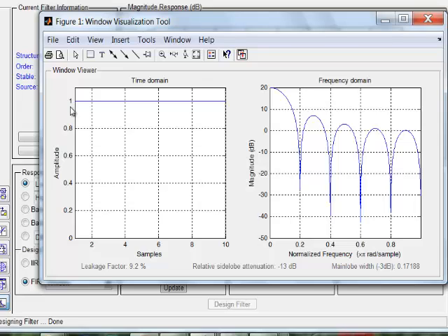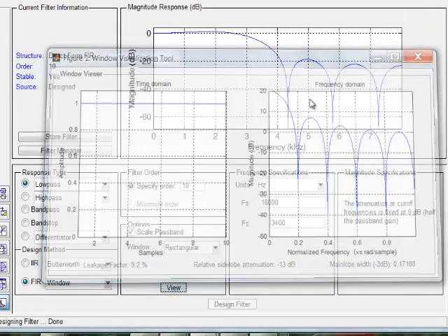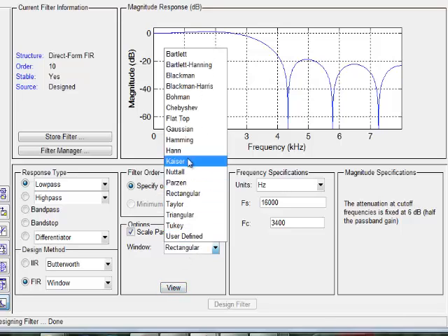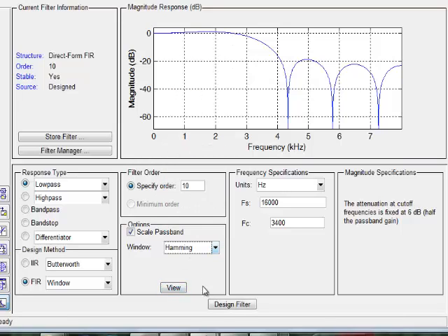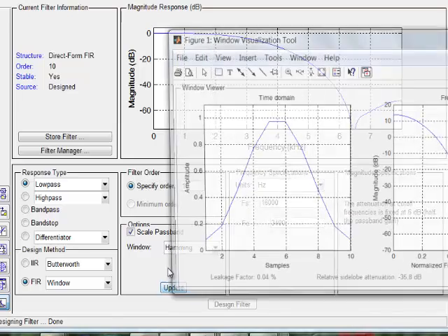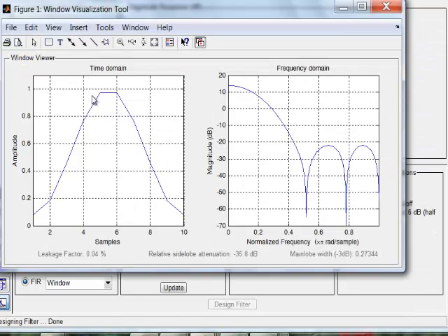In the time domain, the rectangular window considers all the taps, all the elements of the signal, in the same way. But if you're using a smooth window, it means that some samples in the time domain are more important than the other samples in the neighborhood. So you give higher weight to some samples and lower weight to others. That makes sense specifically when you are overlapping the windows.